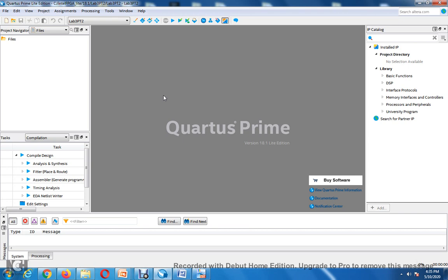To overcome that problem, you would have to temporarily right-click on the FA full adder to make it the top level entity until you finish it, and then change the top level entity to Lab3Pt2.bdf. So that's a quirkiness of this software.